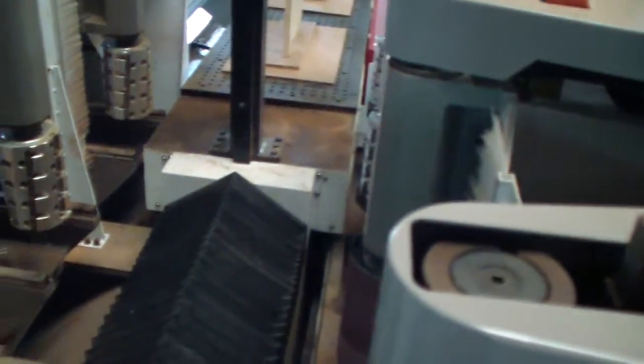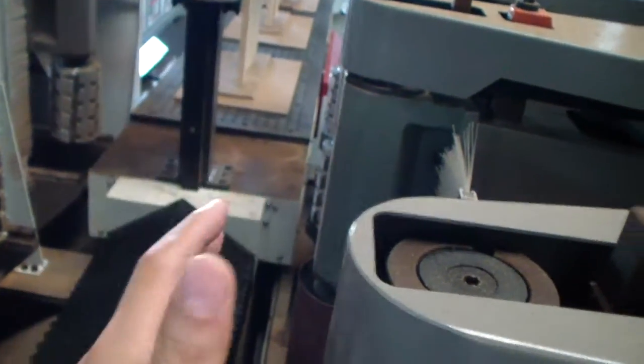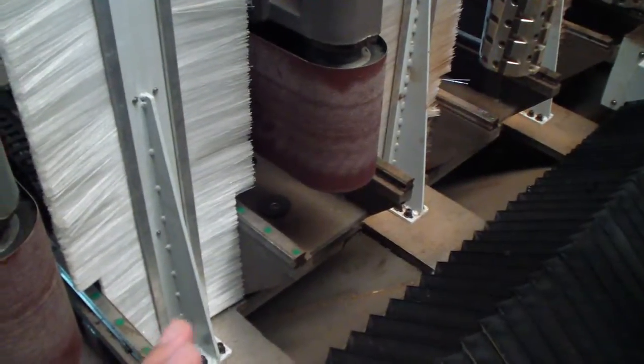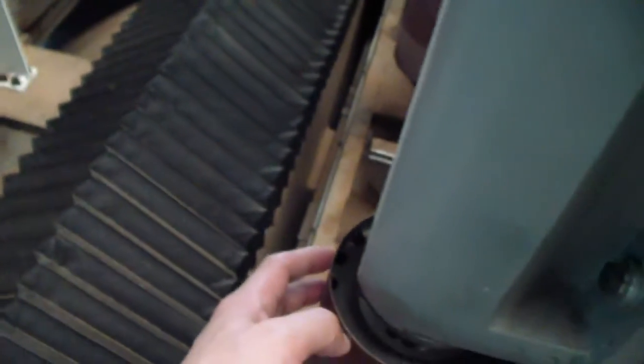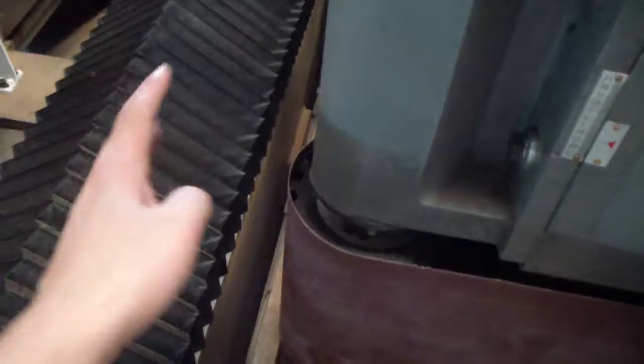Now it is correct. So this is the method for the calibration of the cutters and the sanding belt. Please remember that the sanding belt calibration cannot be done directly with the sanding belt. We need to change the spiral cutter onto the spindle and do the first calibration with the spiral cutter. After getting the correct data for the tools, we can change back the rubber rollers and sanding belt.